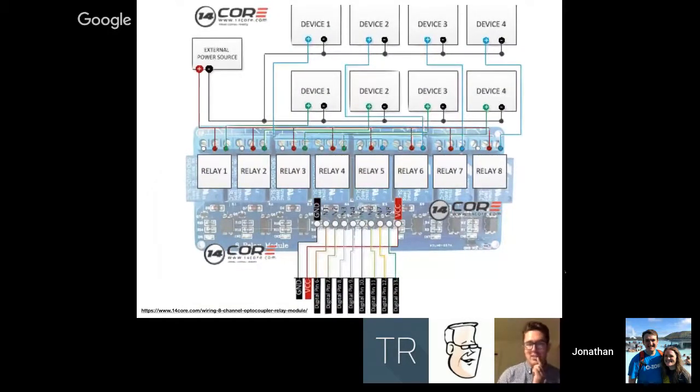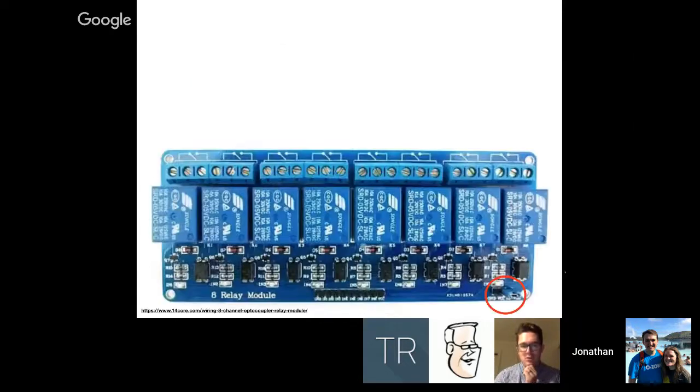Sorry, Jon, can I ask a quick question? Yep. So if you separate those, would that mean that, because there is a 5-volt out pin on the Raspberry Pi, you could use 5 volts as the power that's going to hold the relay open or closed, but you would only be triggering with the 3.3 volt, and it wouldn't necessarily wear down the relay since you're using a full 5 volts for holding it open and closed. Is that right? Yeah, that's my assumption. I did try that too, and it worked. Triggering with 3.3 and then using the 5 volts separately to hold the relays. Awesome. I'll try it out.